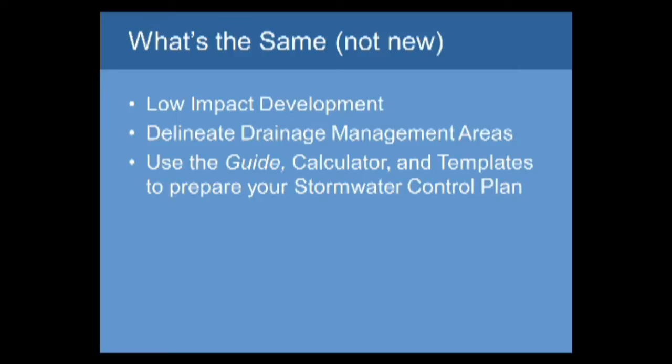So we continue our focus on that as being the main aspect, the first thing that I advise municipal reviewers to take a look at when they first open up a submittal: do they have a diagram of the site showing the entire site divided into distinct drainage management areas, so we can then follow where the runoff from each is going.